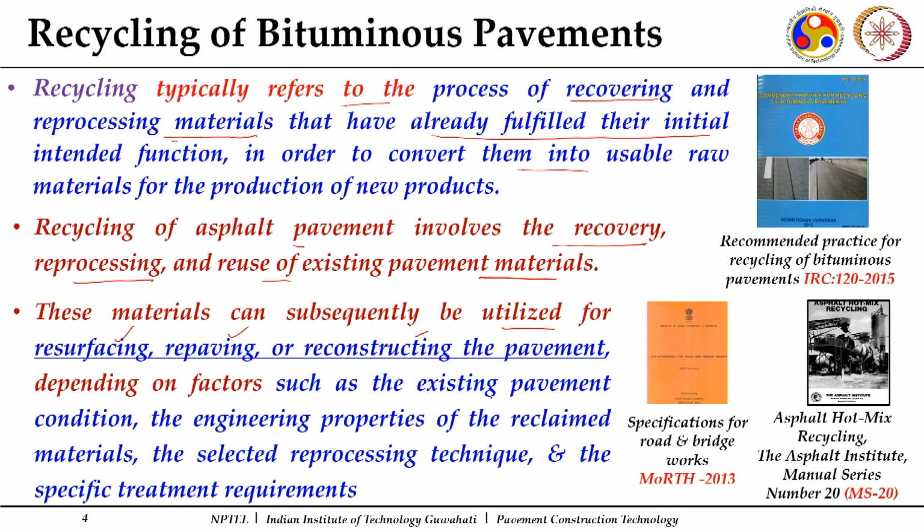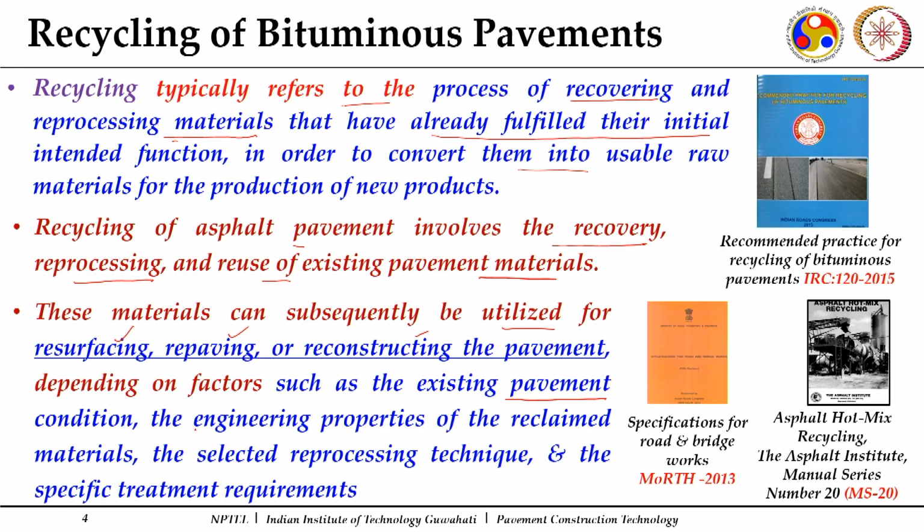All these exercises will depend upon what factors? First, it will depend upon the existing pavement condition. If the defects are restricted to the surface layer, we will process only the surface layer. If the defects are in the underlying base and bituminous binder course also, this has to go deep into those lower layers also. So, it will depend upon the existing pavement condition.